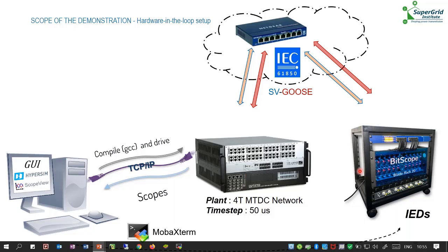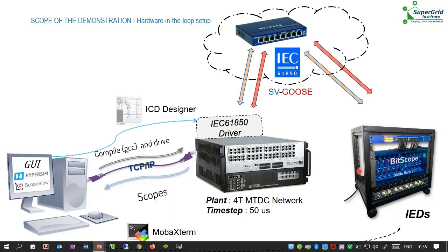So now both IEDs and the target need tools to use IEC 61850. A built-in driver is implemented in the target. However, we still need to feed it files called IED capability description files, ICD files, that we make with the ICD designer software. It is less trivial for the IEDs. The communication has been crafted via an open source C library called libiec61850.